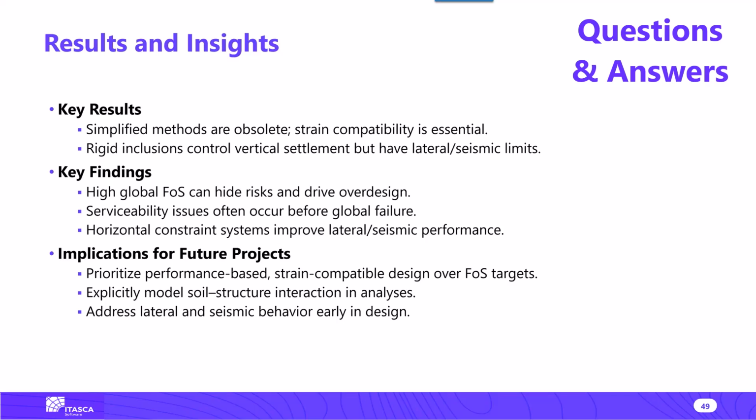So I tend to fix the failure ratio, unless I have a relatively stiff material like a rock or weathered rock or stuff like that. Then I tend to use an Rf lower, in the order of even 0.6 or 0.7, because otherwise I'm not able to get the stiffness that I want.